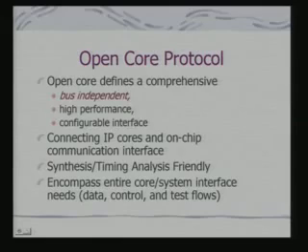This open core protocol, why we are discussing it here, is conceptually different. What it tries to define is a comprehensive bus independent high performance configurable interface. In the earlier case, all your interfaces were predefined and you were making your IP cores compatible with those definitions.